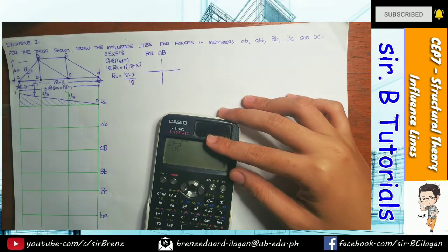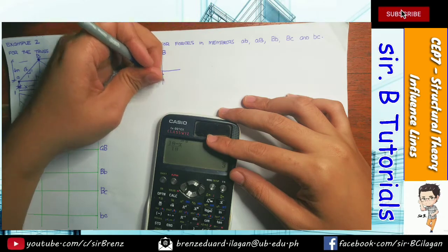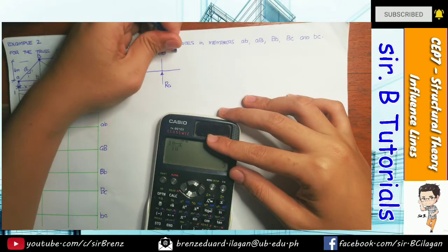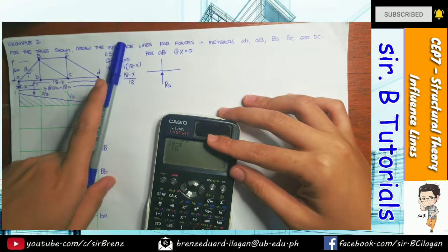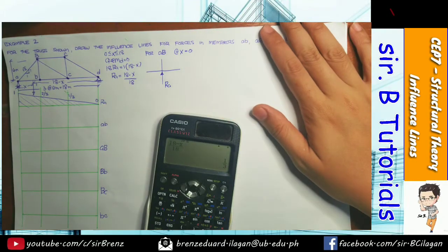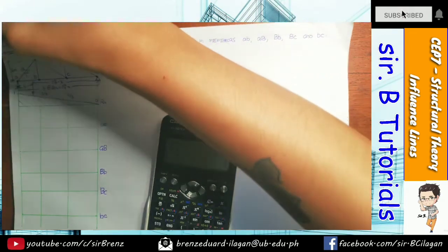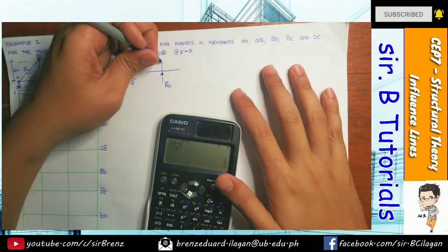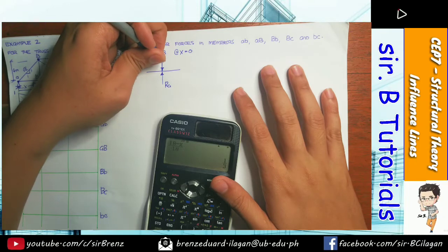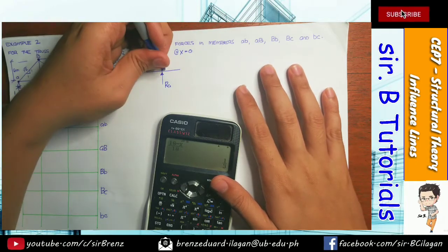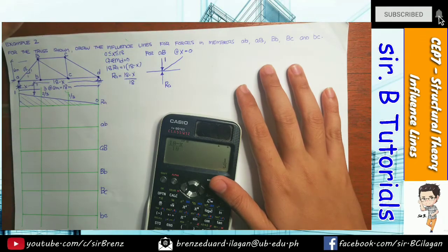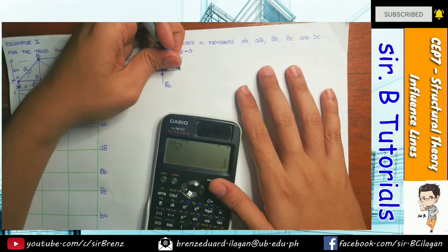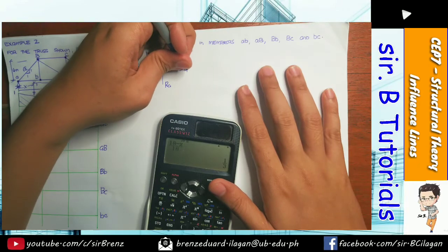What do we see at joint A? Again, we have here your RA. For this, guys, the equation I can make is at x equals 0. So what do you see when x is 0, or the 1 unit load is located at 0? That means the 1 unit load is directly above here. So, 1. And let's assume it is in compression. Okay? So this is your AB, and this one is also your AB.